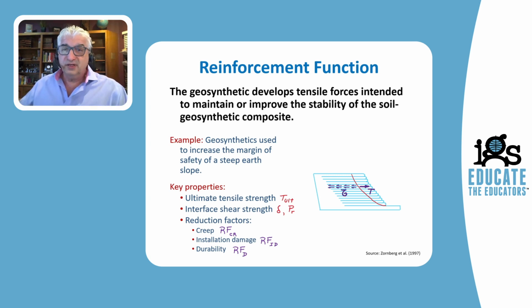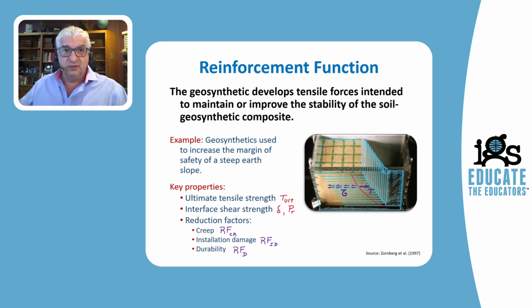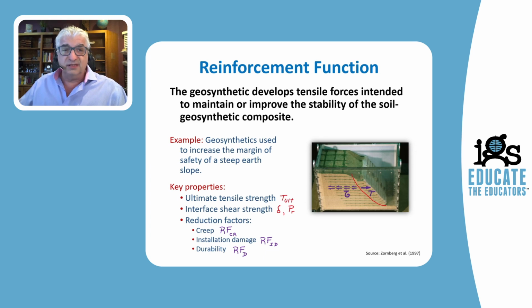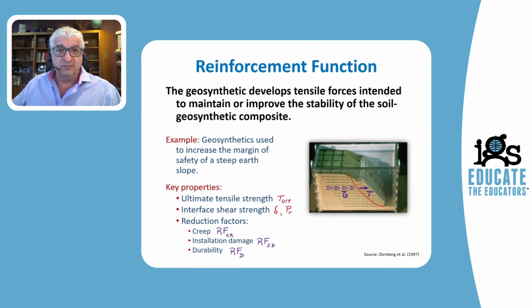This can be quantified with a reduction factor for durability. I thought that it would be interesting to show you that this is not only a cartoon, but it's actually a model that was brought to failure. And here is a full 3D version of the model, but here is the actual model. This model was brought to failure by placing it in a geotechnical centrifuge. What is interesting is that the model failure is very much like the one that is considered in the design. The models failed because of having achieved the tensile capacity of the geosynthetic reinforcements.